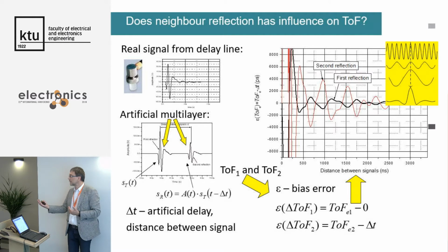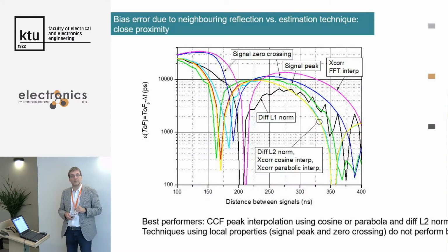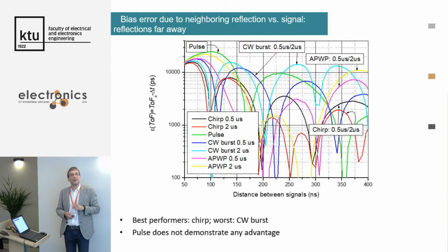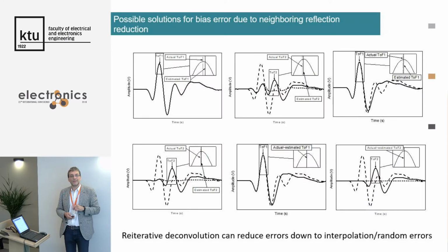But once you sum two sinusoids with different phase, you have a sinusoid with a new phase, and none of the measurements is satisfied, and you have errors in both cases. What to do? We have tried several techniques, and we have found out that iterative deconvolution somewhat reduces the errors, but then we have realized that there is another technique.